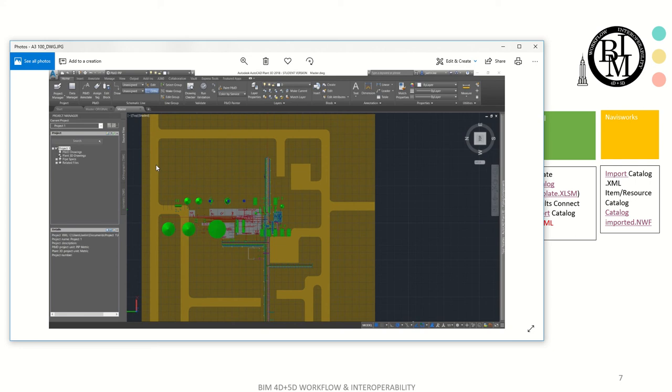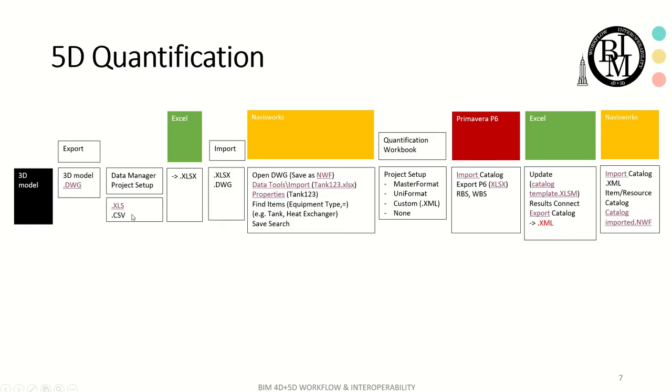And you can export those in the form of an Excel file. Once you export it, you have an option to export it in 2 different file formats, and I chose XLS. And you will have to resave it as XLSX. Then it becomes available to import to Navisworks.